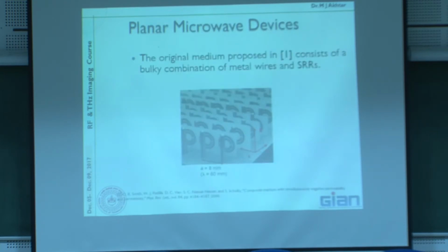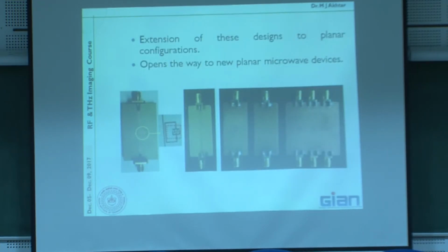This is what people proposed, but our main thing is something like this. If you can see it clearly, this is a microstrip, and I just make a resonator on the top. This is a typical split-ring resonator. And this is the backside, this is complementary. So if I put a metallic ring on the top side, this will be what we call a split-ring resonator. If I put it on the backside, it will be complementary, and this is many of them put together. These structures are what we call SRR or CSRR based resonators, or we can also call them metamaterial inspired sensors. Now let's see how they can be used to sense or determine the material properties.